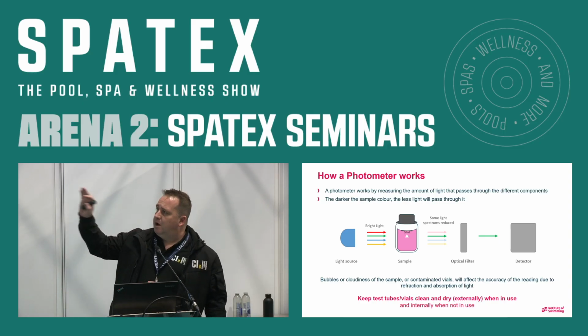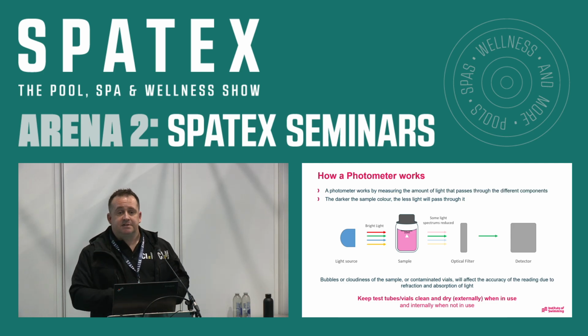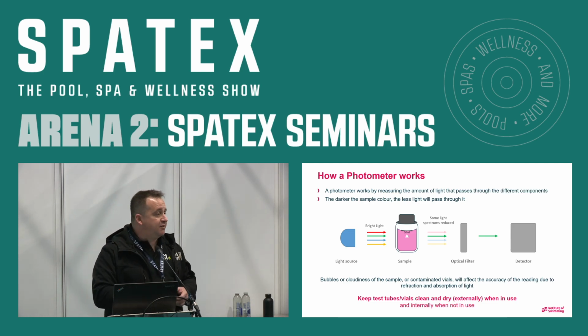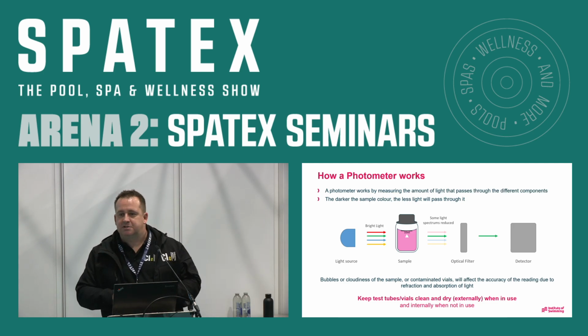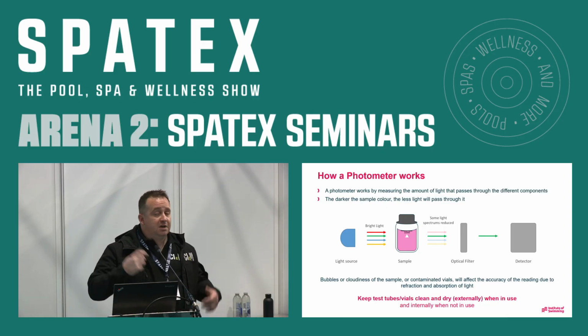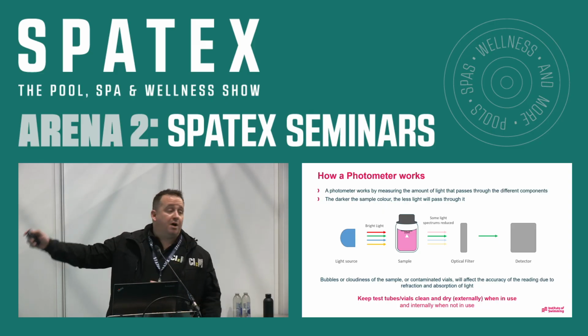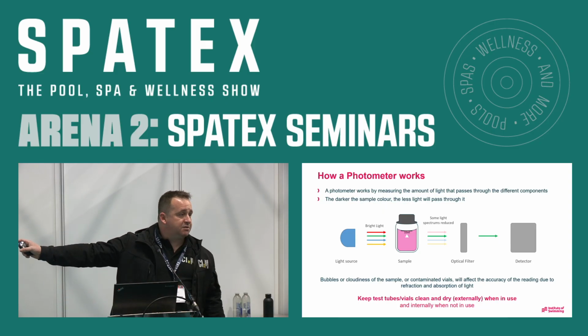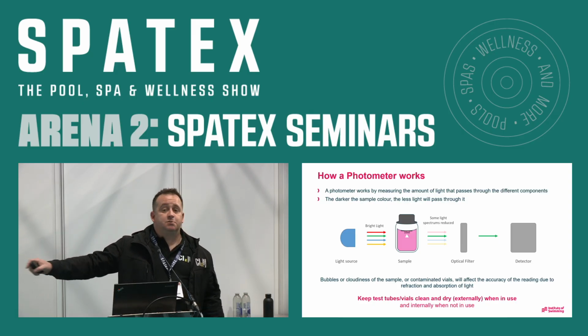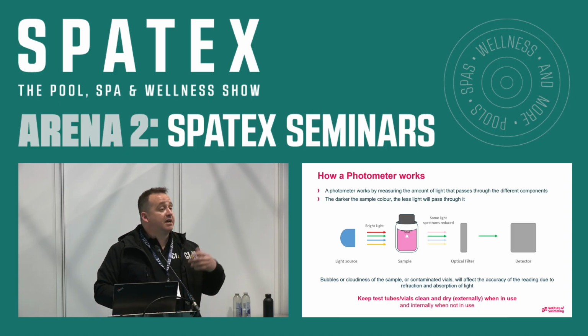With some of the older testing, we used to have to shake the cells to help the tablets dissolve. If you do that with a photometer cell, you're going to get tiny little bubbles in the liquid, and that is simply going to affect what the machine sees. So no shaking. Crush, swirl by all means, but no shaking. And my personal bugbear as well: always dry them out after use. When you finish with your cells, use a bit of blue roll, inside out. I know it's a pain, but dry them out. Don't leave them to drip dry or with the sample still in them, because that's just going to stain the glass and cause more problems from there.